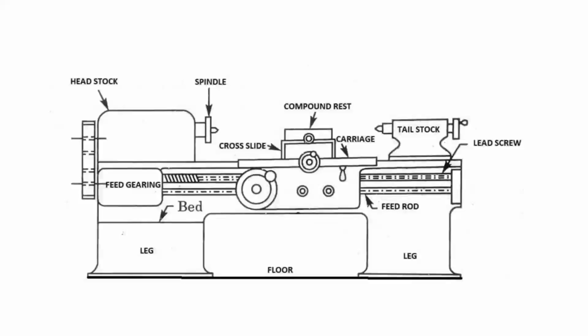The material of the bed should have high compressive strength, should be wear resistant and should absorb vibration. The material which is selected for the bed while casting also needs to be inspected, so that the casting of the bed will be proper and there will be no deflection on the bed when it is used in machinery. In this point it is given that the bed should have high compressive strength, be wear resistant and absorb vibration. Such material is to be selected.